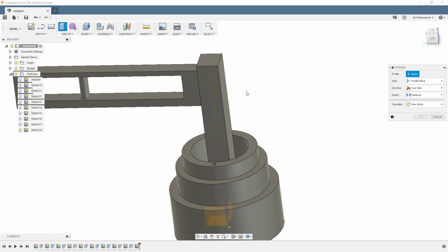So I hit E for extrude, and I go to pick that shape. And this is common to all types of things in Fusion that you want to do. Hold down button number 1, your left click mouse button. Hold it right over the top of the thing that you want. Imagine right where your mouse point is, if we drill a hole right through the entire part, any face that's in its path will show up here.